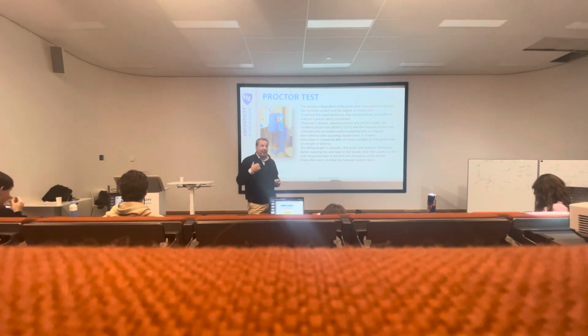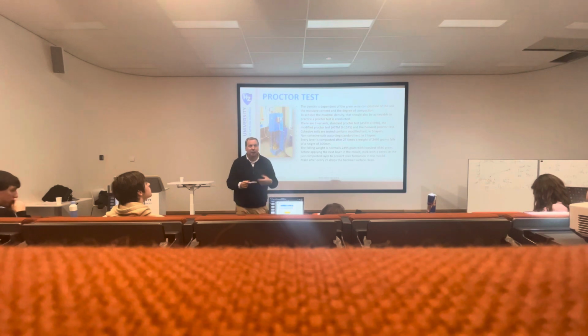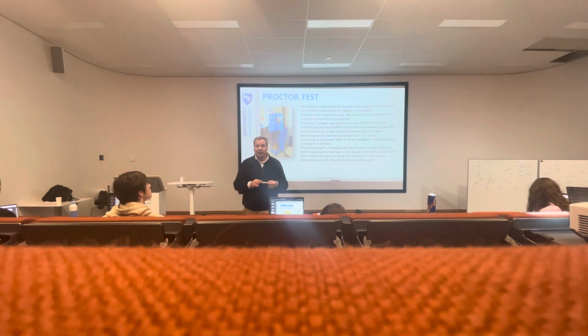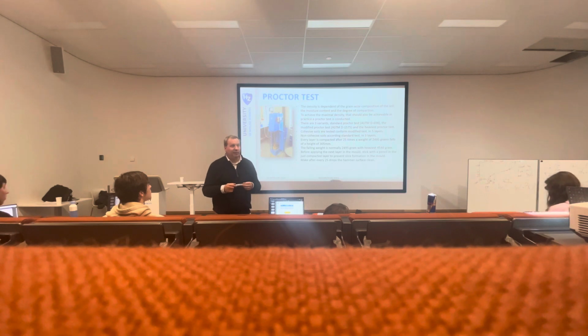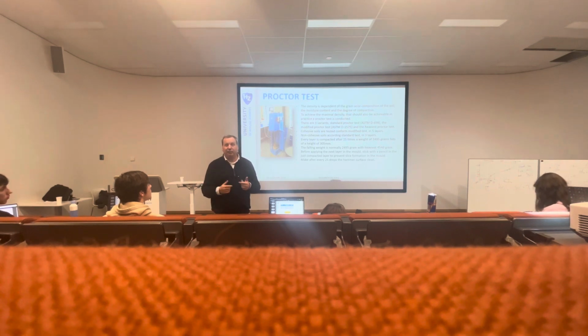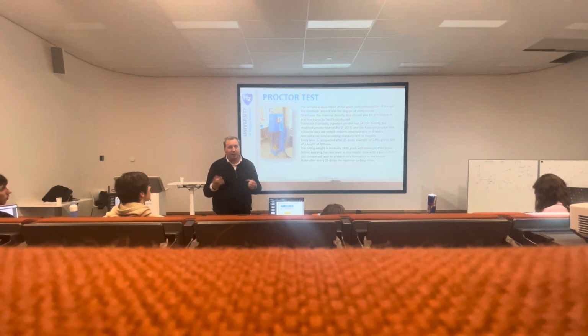And then on site, later on when the project will be executed, you have to say, you have to put a water content of the soil of 8% or 10% so that you can compact it well. If it starts raining that day, you don't want to add water, please. And if it's very dry and you have to mix it, add a little bit of extra water. Therefore, you need a little bit of experience.